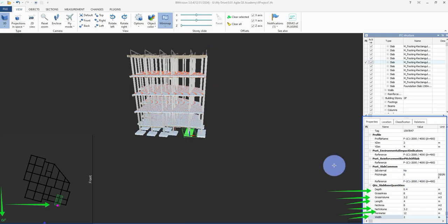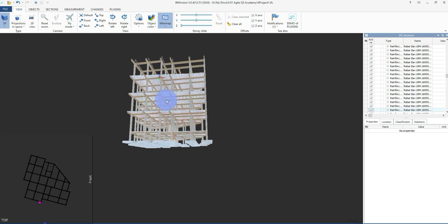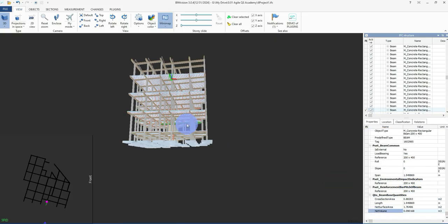So I believe now you see how you can navigate very well in the model and the amount of information you can be looking at. So let's try some beams as well. You can just come on this and click on any of the beams. It's giving you the second floor and all the information. If you don't visualize it very well, you can come here and see it. You can have the QTO, the quantities, for that specific beam.